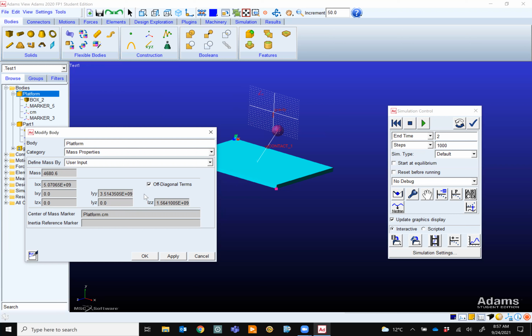This matrix is 3 by 3, but it is symmetric. For now, those are 0, we don't care about them. But if one of the axes is symmetric, then Ixz or Ixy with that one will be 0. So this is the mass and Ix, Iy, Iz based on steel.